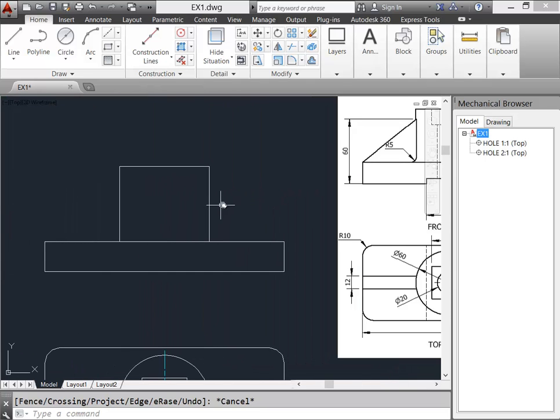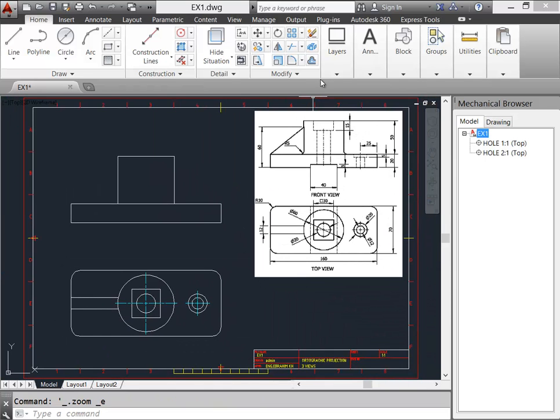So I'll use an offset tool again, type down 60 from the bottom of my base up. This is only a line in order to determine the point where my web ends. So I'll pick line again. This is my web beginning, and here it ends.